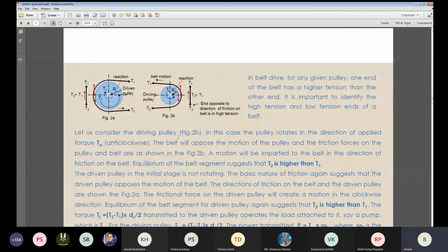So in this power transmission, who is the mediator? The mediator is friction. Friction is just mediating the initiation of the power, for which the belt starts rotating. That is the reason in T2 minus T1 we are considering an impending slippage. If it is slipping, then everything is gone, no power transmission. Just before slipping, the contact friction is a little lower than the slippage friction, so the belt is automatically, by virtue of friction, rotating. The belt is getting drawn by this pulley.